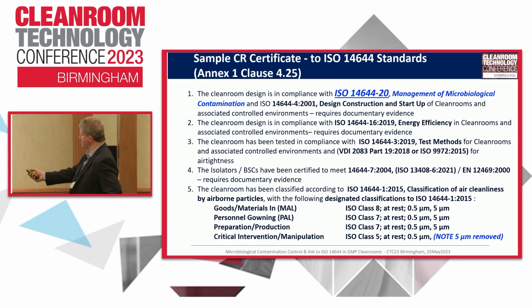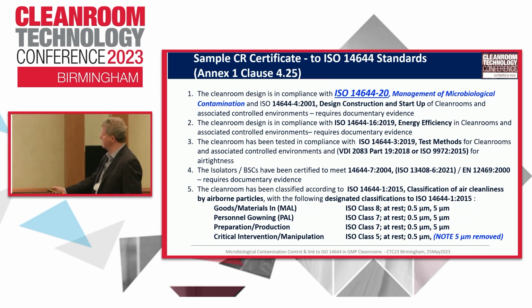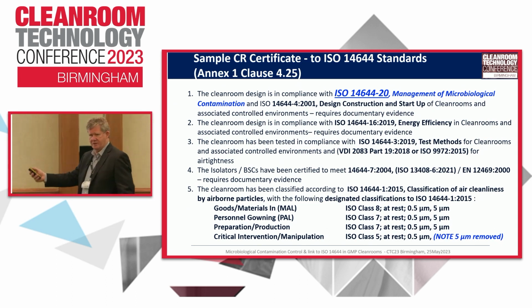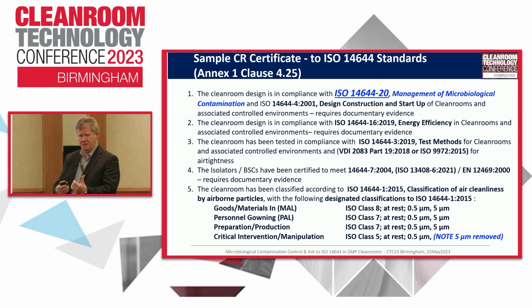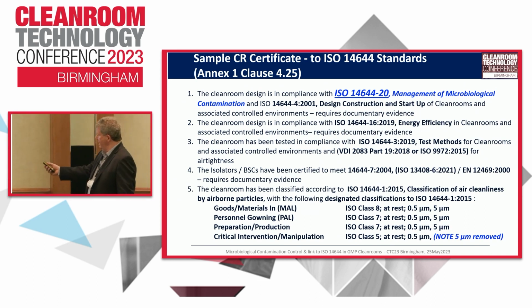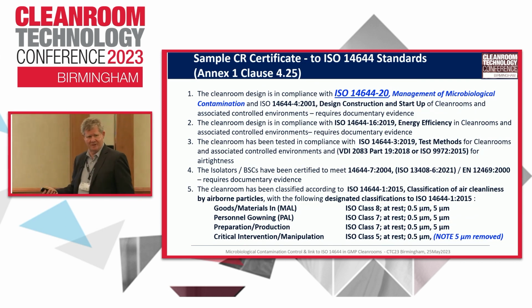So I'm suggesting this is how you link the 14644 standards. I've put in blue the -20 because it's not out yet, but in the future, you want people to say to you, yes, I've taken into account the standards to design it for microbiological cleanliness in air and on surfaces. And I've applied -4 and -16 and -3 and all these other dashes, but they're the relevant ones here. I've probably missed a few, but they're minor players. And finally, it's certified to -1. If you call it a clean room, you must certify it to -1.